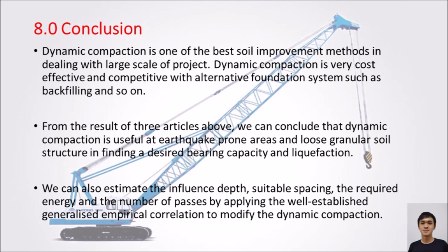Okay, overall, we can conclude that dynamic compaction is one of the best soil improvement methods when dealing with large-scale projects. Dynamic compaction is cost-effective and competitive with alternative foundation systems such as backfilling and so on. From the results of the 3 articles above, we can summarize that dynamic compaction is useful in earthquake-prone areas and loose granular soil structures in finding a desired bearing capacity and addressing liquefaction.